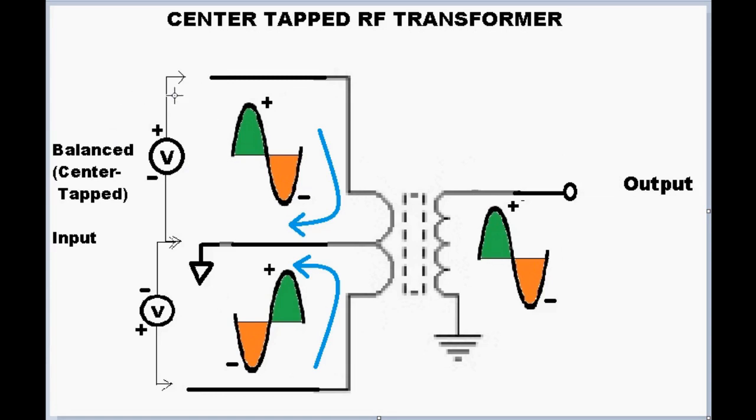You can see that the upper transistor will create a current flow this direction, which will induce a positive voltage across the air gap and into the secondary, positive pulse. And in this flow, going the opposite direction, we can see that since the flow is in the opposite direction, the voltage set up across the primary and the secondary will be in the opposite polarity, negative.